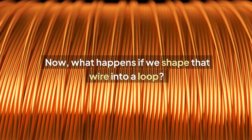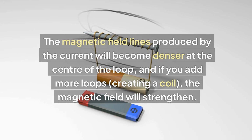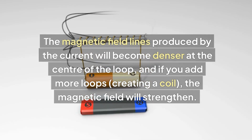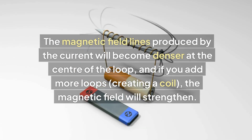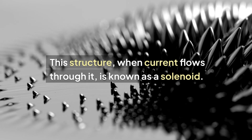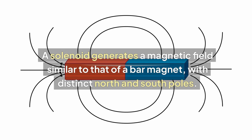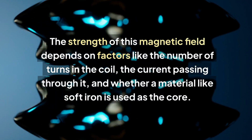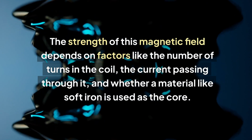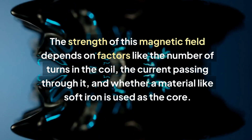Now, what happens if we shape that wire into a loop? The magnetic field lines produced by the current will become denser at the center of the loop, and if you add more loops, creating a coil, the magnetic field will strengthen. This structure, when current flows through it, is known as a solenoid. A solenoid generates a magnetic field similar to that of a bar magnet, with distinct north and south poles. The strength of this magnetic field depends on factors like the number of turns in the coil, the current passing through it, and whether a material like soft iron is used as the core.